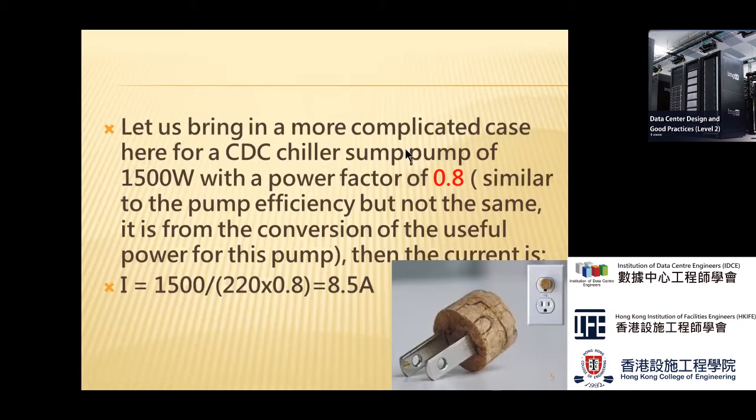However, if the power factor does not equal 1, like most electrical mechanical plant which rotates, like fans, pumps, chillers, generators, right? So anything that moves or rotates, you have a power factor, either 0.8 or 0.9, or sometimes they claim 0.95 or 0.99, whatever it is. We need to find out from the catalog or from the supplier.